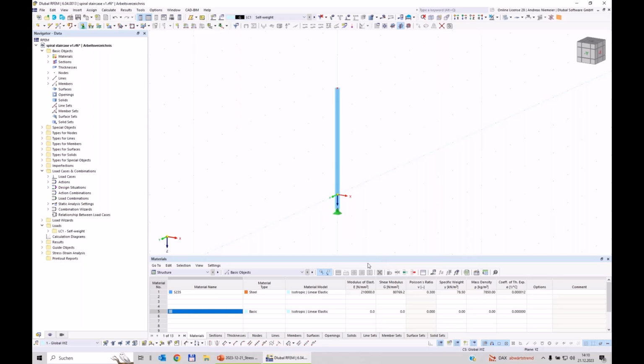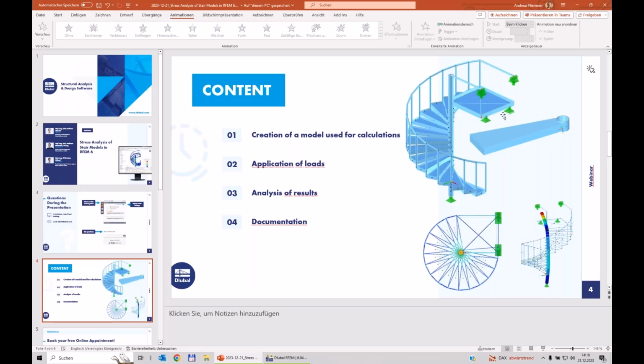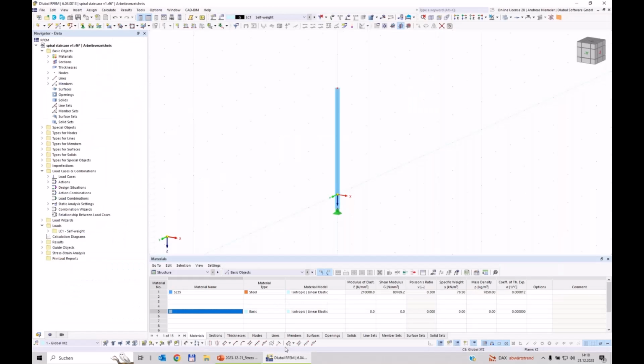Next, we can think about how we can apply these prefabricated stair steps. And these stair steps, maybe only so that you get a picture, it's this element here. And here we start, or let's say we define a level where we want to place it. For this, I use my working plane, and it's, let's say, 8.5 centimeters above this point. I want to open the topic of how you can move your working plane 8.5 centimeters upwards.